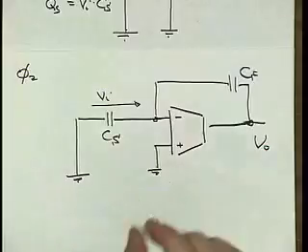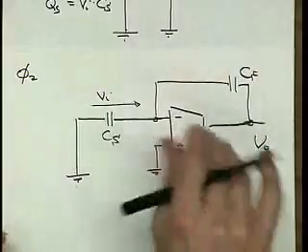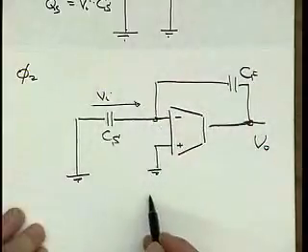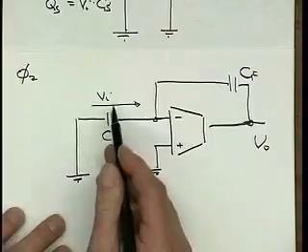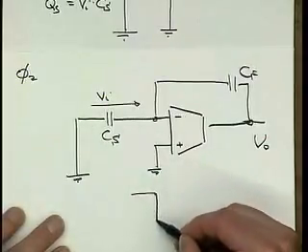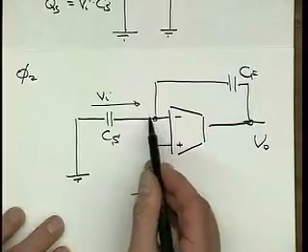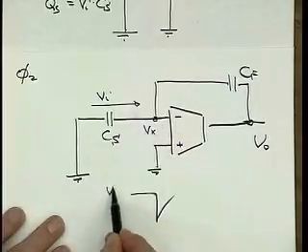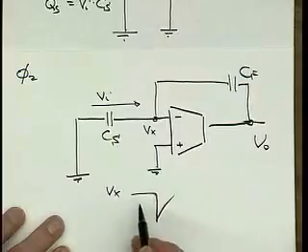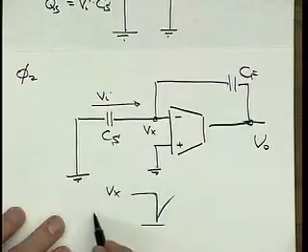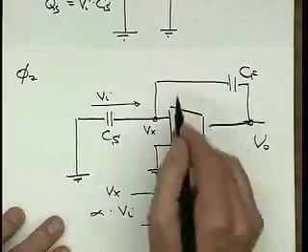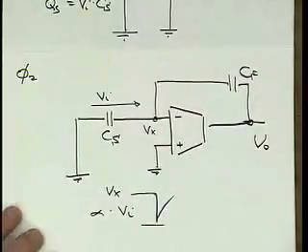So just when we close the switch, there is some capacitive division and so on, but at any rate, we are going to see a blip. If Vi was positive, then the voltage at this terminal here, Vx, is going to drop from 0 down, and the height of this drop is going to be some factor alpha times Vi, and alpha really depends on how much capacitance we have there. It's less than 1. It's nothing of amplification.